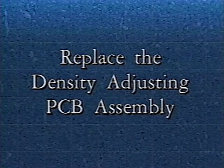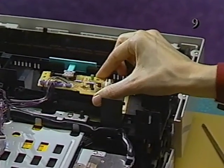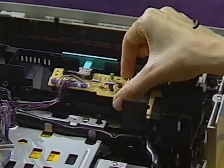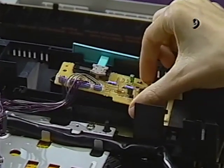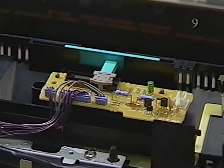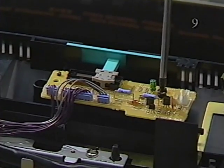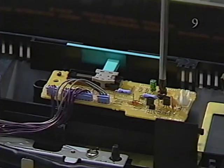Replace the density adjusting PCB assembly. First, place the density adjusting PCB in position next to the fan. Replace the two black screws and washers that hold the density adjusting PCB to the inner cover.